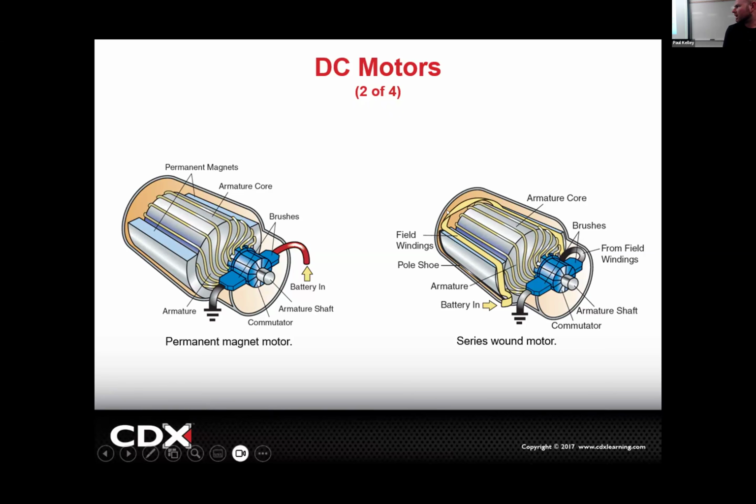If you had one bad segment in this motor right here, it's only a probability before it lands on the dead spot next time, right? So typically what I'd see is maybe about eight segments in the motor, and if one fails, you got 7 good ones, right? So a lot of times, probably 7 out of 8 times, it'll work. But then 1 out of 8 times, it happens to stop on the dead spot, and it won't work, and the 1 out of 8 times happens to be in the Walmart parking lot.